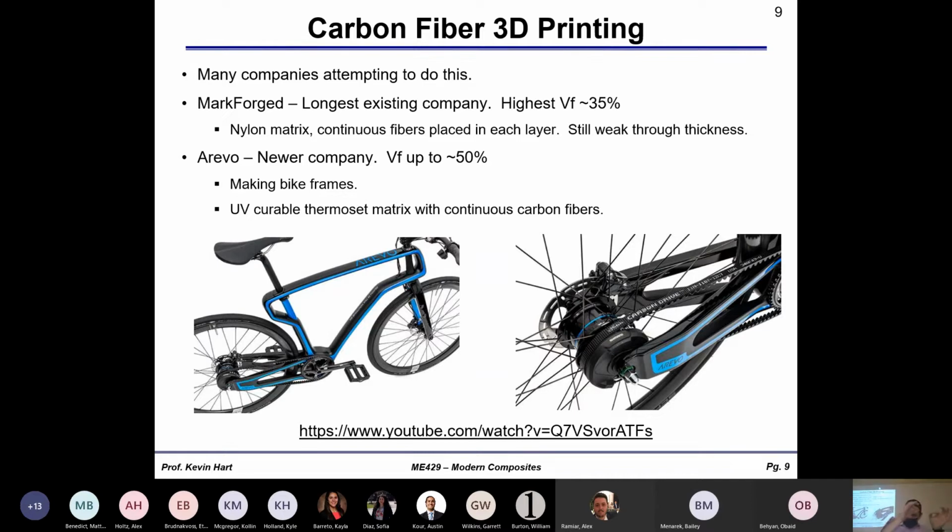So it's this continuous process where they're laying down fiber, following it with a UV light to partially cure it as it goes. So layers are partially cured, bonding to each other. And then at the very end, they take the entire assembly and put it in a UV oven for some amount of time, probably like a day, to fully cure that UV curable resin on the inside.